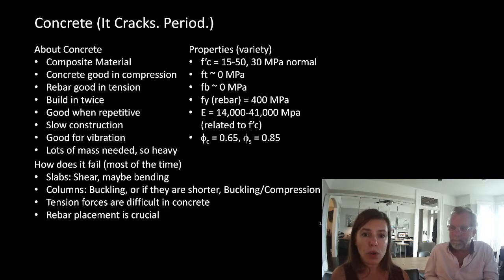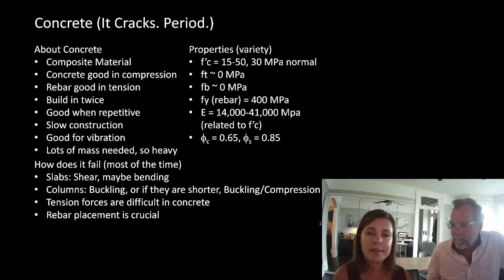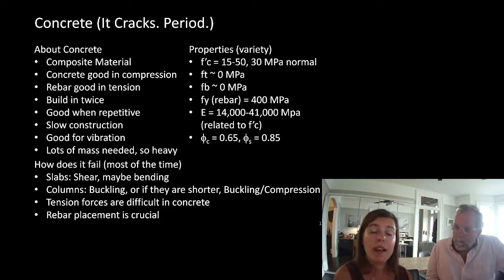With concrete, we have to build everything twice. First, we build a wood version of the structure. Then we fill it with liquid concrete. The concrete cures. And then we take away the wood structure. So what makes concrete usually the most affordable is the fact that we build with the wood portion multiple times. Now, obviously, probably for a lot of landscape elements, that wouldn't be the case. We would just use it as formwork and then take it away.